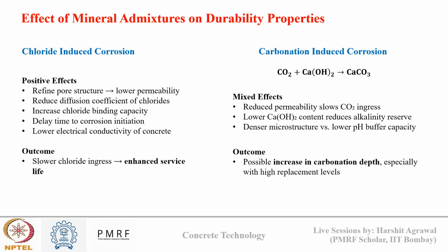And finally, we discussed how durability properties are affected by SCMs, where due to pore densification, all SCMs reduce the rate of chloride diffusion after prolonged hydration ages. However, in terms of carbonation induced corrosion, due to consumption of calcium hydroxide by the secondary pozzolanic reaction of SCMs, they increase the carbonation depth. So it is a mixed effect. They are reducing the permeability to CO2, but at the same time they have also consumed CH which reacts with CO2. Okay, so this was all from last discussion.